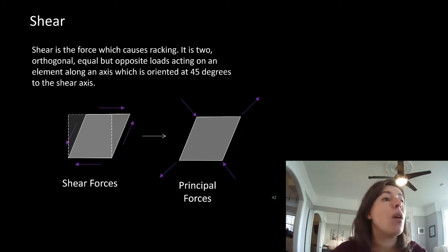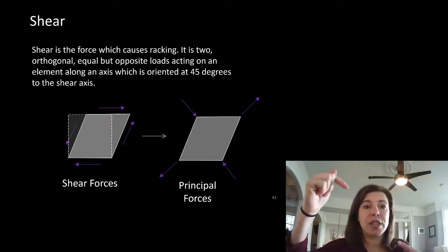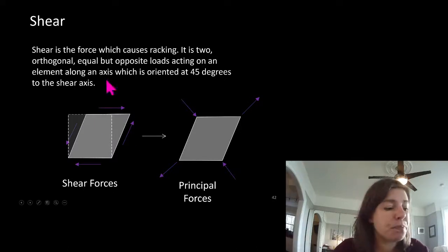So this stress is very similar to equal and opposite loads acting on an element oriented at 45 degrees to the shear axes. So shear axes, 45 degrees, compression, and tension.